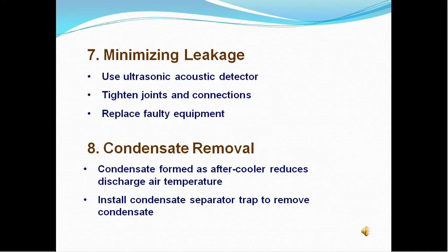Minimizing leakage. Compressed air leakage accounts for a substantial power wastage. The best way to detect leaks is to use an ultrasonic acoustic detector that can recognize the high-frequency hissing sounds associated with air leaks. Leaks occur most often at joints and connections. Stopping leaks can be as simple as tightening a connection or as complex as replacing faulty equipment.